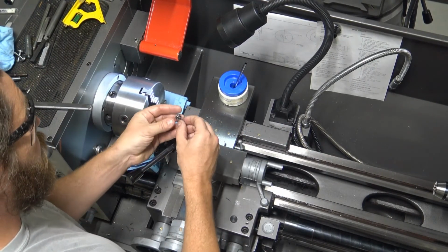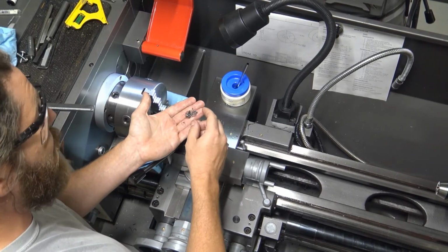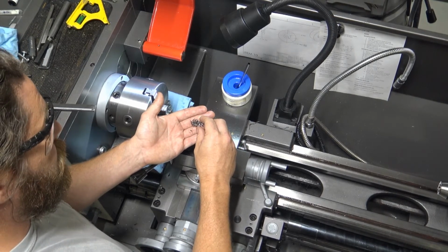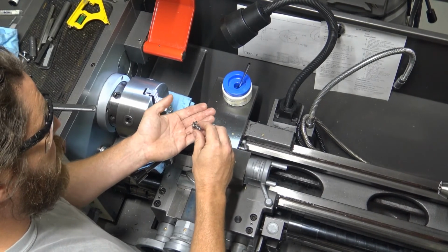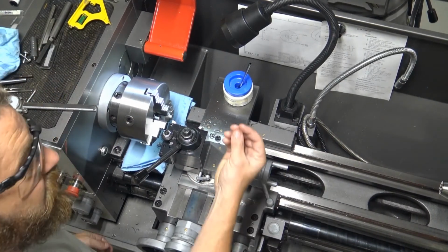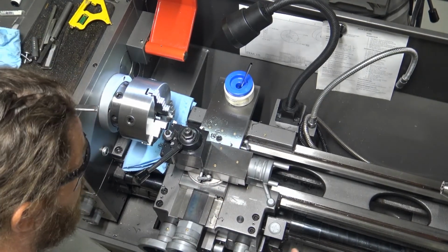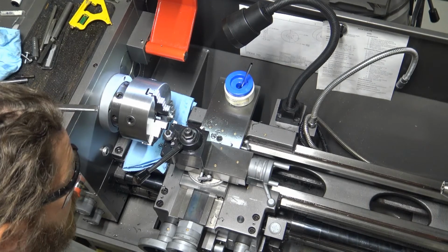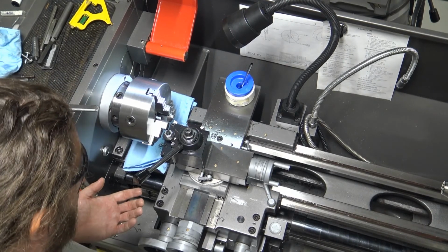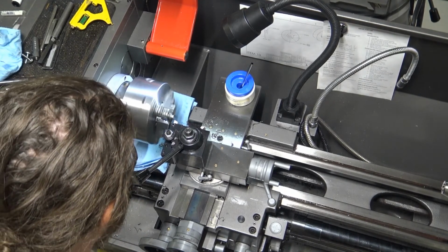All right. So if you're cutting too fast, this metal will start turning black or purple, and you're heating it up a lot. If they're turning black on you, you may need to slow down. If they're small and crumbly, you need to speed up. All right. It's all a feel thing. You'll get used to it. So I've done 5 passes. I'll need to do one last pass.